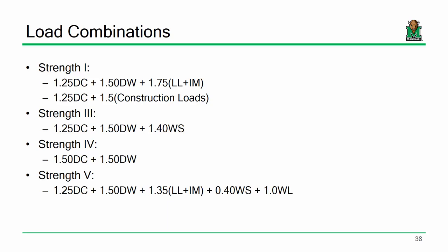Like I said earlier, once you get something in the spec, it's really hard to take it out. And a lot of engineers really didn't like LRFD when it first came into the limelight, because LRFD is more complicated than allowable stress. Take a capacity, divide it by 2, and there you go. It seems simple. It's also not as economical, so that's sort of what sold it.